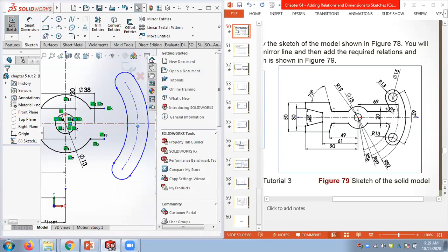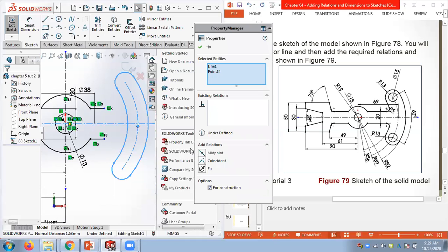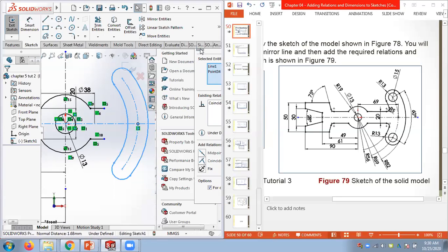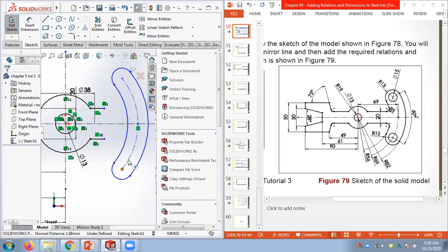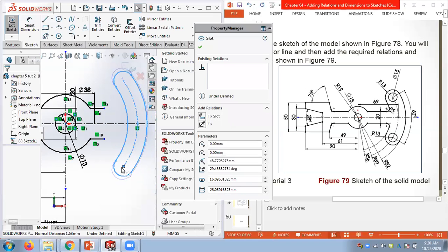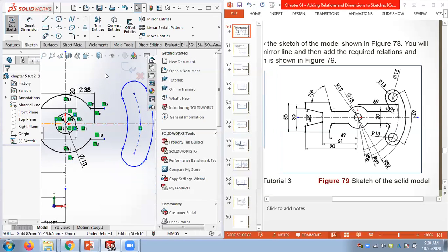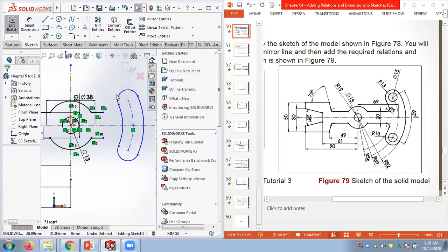So we can click here and click on this one and make it coincide. Then it's aligning nicely. You can see now it's symmetric because I aligned the center point with the horizontal line. Now it's symmetrical automatically, so I don't need to worry about symmetry so much. Then we can apply these radiuses: 82, 69, 56.